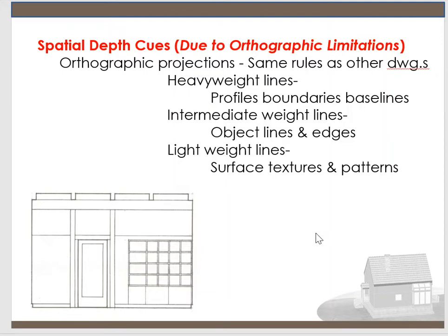But as I said, you also need to know heights. How high is this window above the floor? How high is the window? Now we know how wide it is, but we want to know how high it is. So if it's 2.5 feet above the floor and it's 4 feet, we need to know that information. We also need to know how high the ceilings are. Now, most doors are about 7 feet, and so that's standard. So that helps us out. But really, knowing these heights is key.